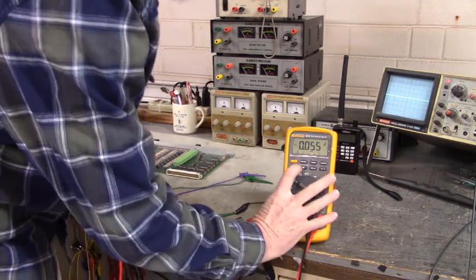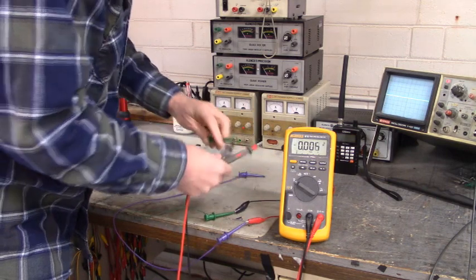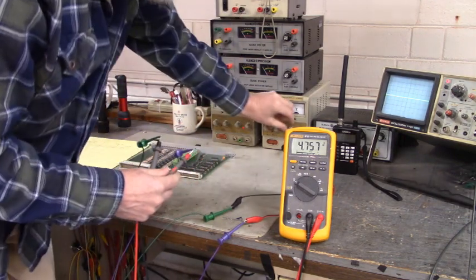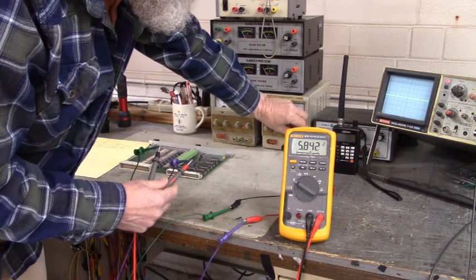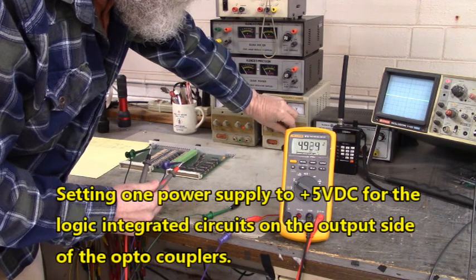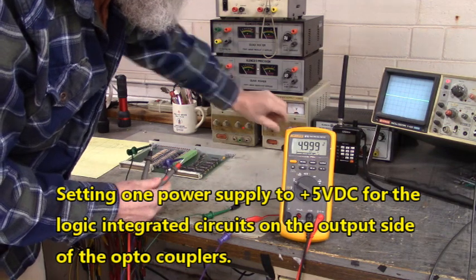You can't get these mixed up. You can't put 24 volts on the 5 volt side, and you can't put 5 volts on the input side. You put 24 volts across those CMOS ICs, and you'll be replacing all of those integrated circuits, so be careful here. Be very careful here.